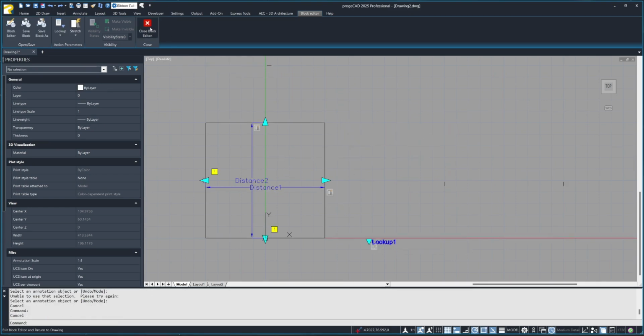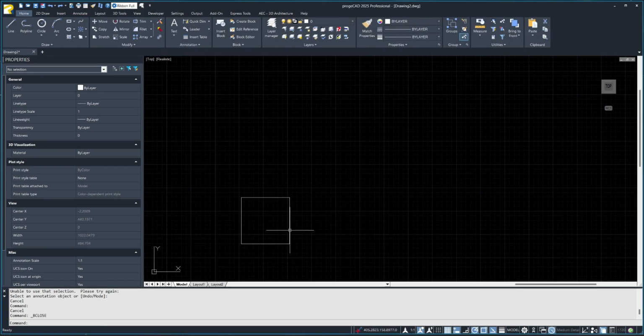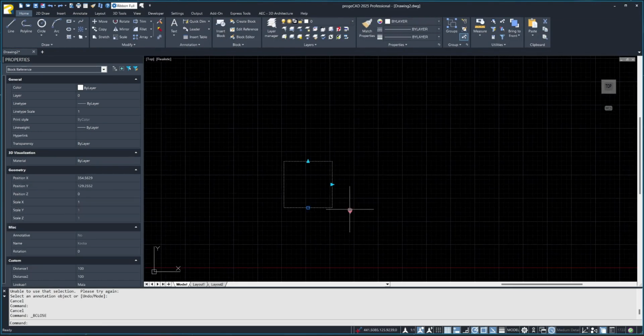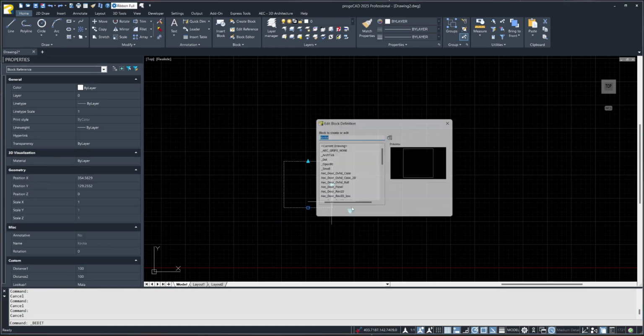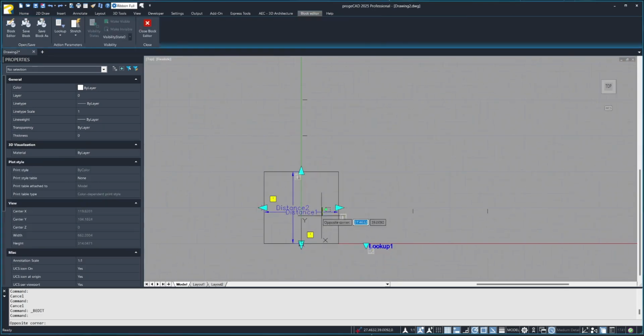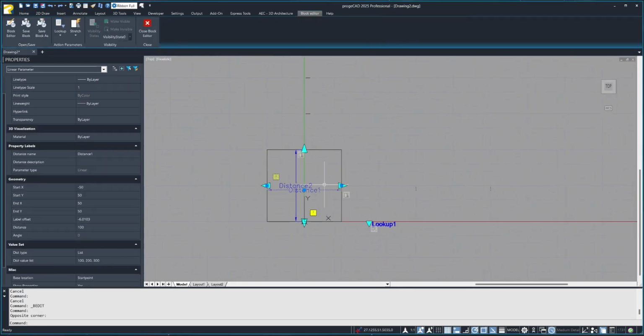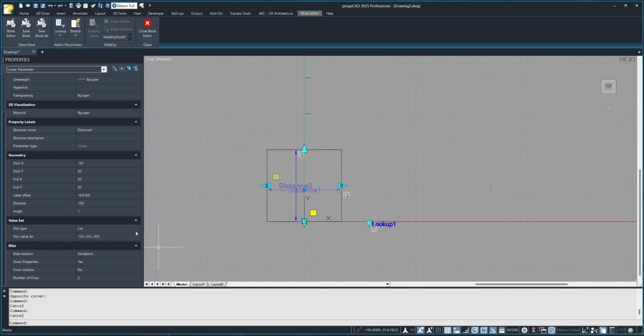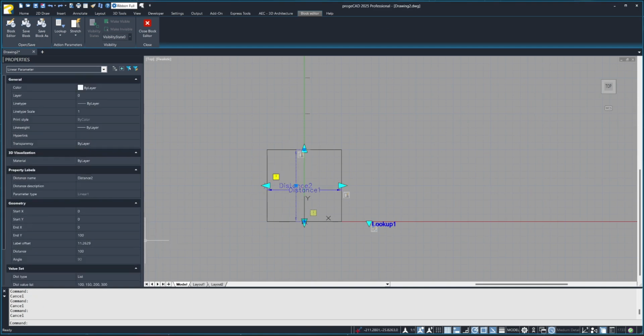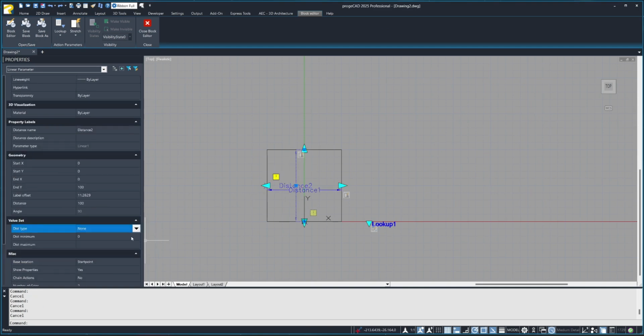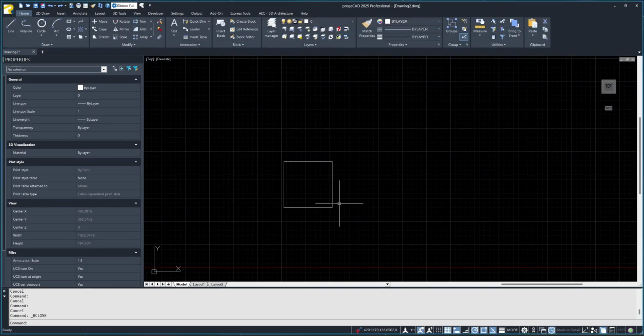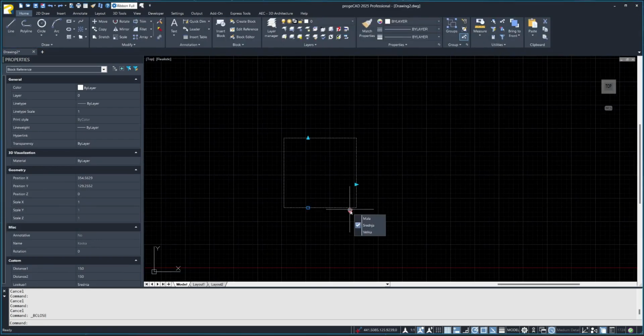Here we can set the smaller distance as small, and here we'll set it as medium. And here we will put large. If we click OK, we close the block editor, save changes, and go to our cube. Our lookup table will have those values that we can increase. For this distance, we placed a list that limits those values, so it doesn't allow us to have that increase. We'll set the list to none and do the same for the other distance. Let's test it now. Everything works fine.